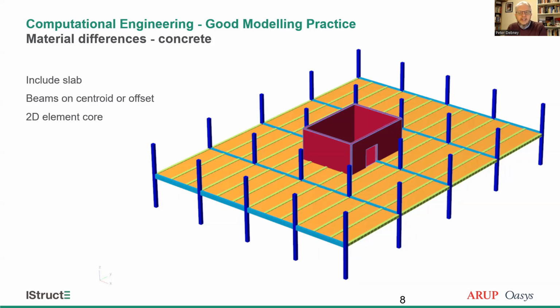If you want that T action, you can offset the slabs up and the beams down, or explicitly model T sections, watching out for the overlap of the two. Just remember, if you do start offsetting the beams and slabs, you will get in-plane forces in the slab, and you will need to make sure that that is designed for.